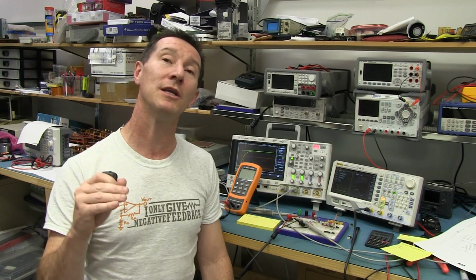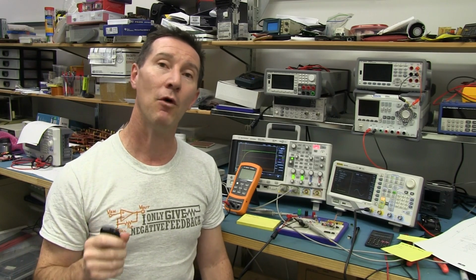engineers know about, because, well, they just throw their capacitor in, they assume it works. They know about all sorts of other characteristics of the ceramic caps and all your temperature coefficients, and mainly all they care about is temperature, but what a lot of people don't think about is that capacitance can change with voltage as well. Not only DC bias voltage can have a drastic effect, but also the applied AC voltage.